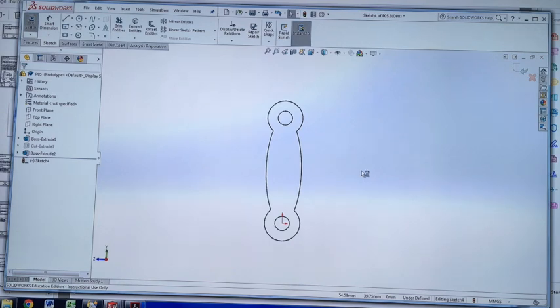So it's in the next step, after we've exported, that we would tell it how deep to do each of those layers, okay, which layers are going to be engraving or etching into the surface, and which layers are going all the way through. For the process of the laser cutter, there's no depth cut, all right? So we can't say, oh, I want a laser cut 0.2 millimeter deep. The way the laser cutter works,